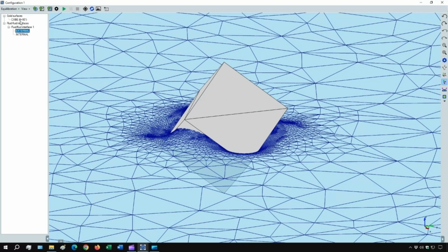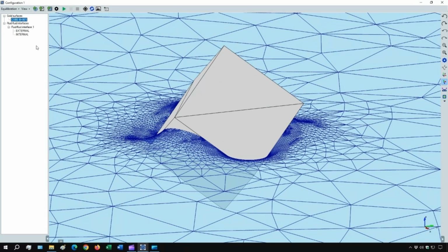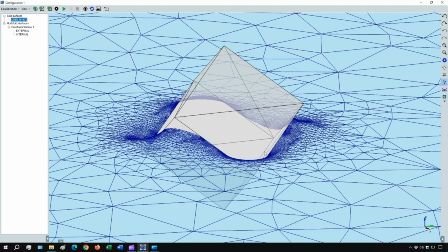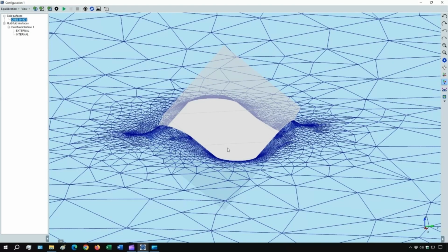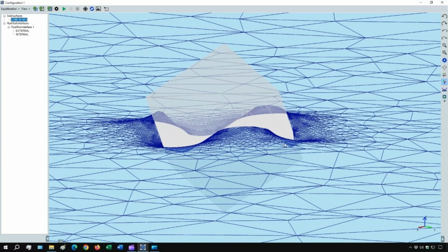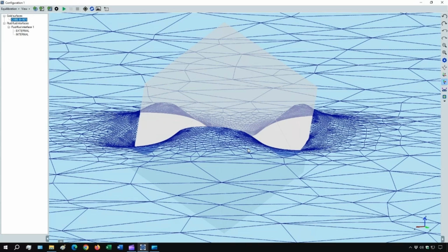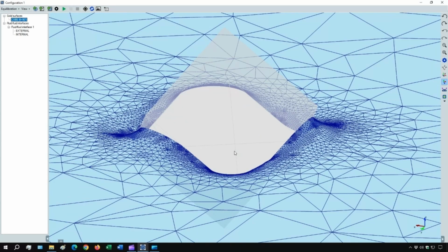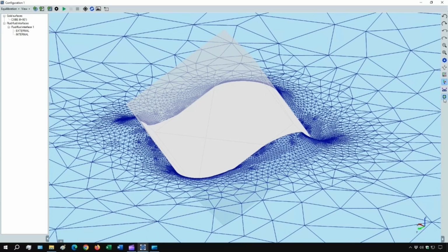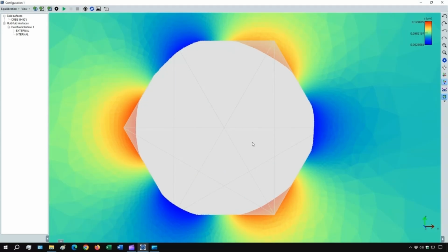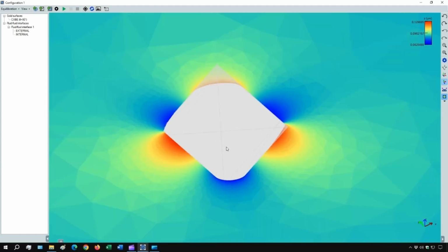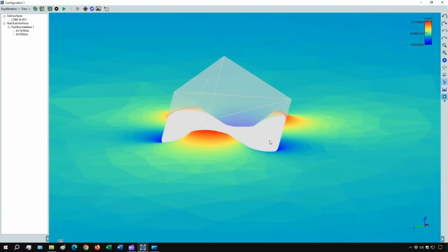The simulation was quick because, firstly, the three-phase contact line of the meniscus along the cube has a simple and smooth shape, despite the sharp corners of the cube. Secondly, the meniscus initial shape was already close to the equilibrium shape. Now instead, I will show an example where the fluid interface's equilibrium shape has a more complex shape.